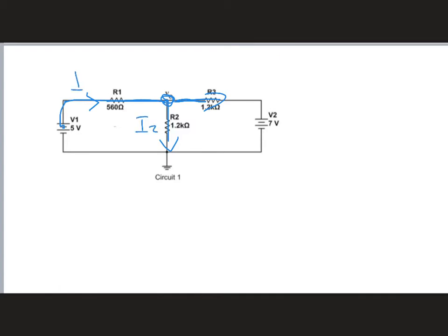The current coming out of the battery, I'm going to label as I1. And the current going through this R3, I'm going to label as I3. Now this I3 continues through this loop. It goes through that battery as well, so this is still I3 here. And then it continues. Now what happens at this junction? I2 and I3 combine, and they come back to be I1. Now technically we should say that that's I4 there, but clearly just by inspection we can see that that's going to be I1. So we can save ourselves a little bit of time by skipping that step of labeling that as I4.